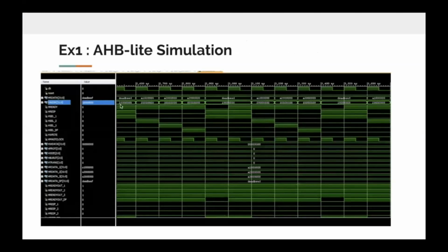As we can see here, for address 1, the data A1 comes 1 cycle after, 2, A2, 3, A3, etc. As for F00, this is an invalid memory location. That is why the slave responds with the data deadbeef and issues an error signal over those 2 clock cycles according to the AHB error protocol.